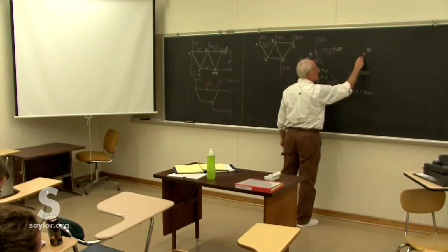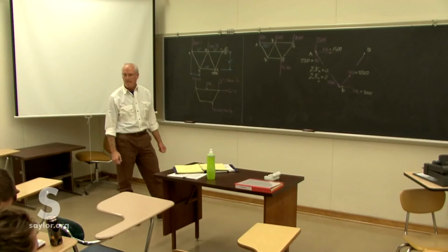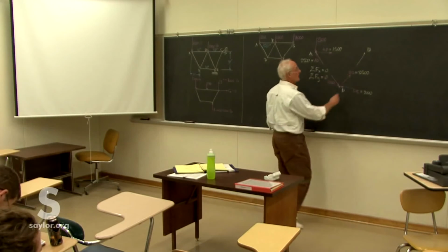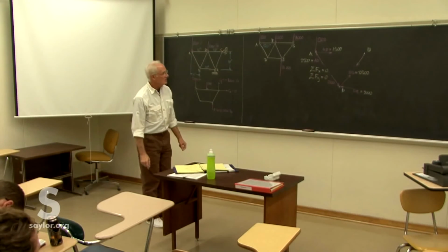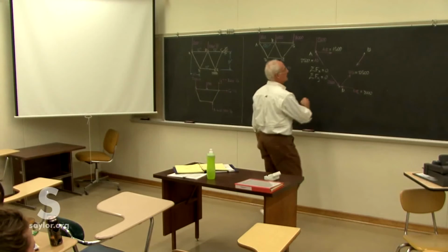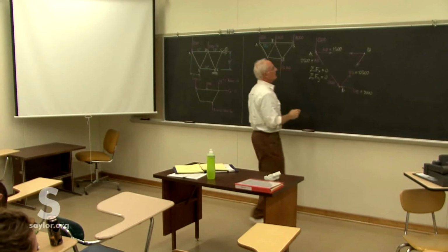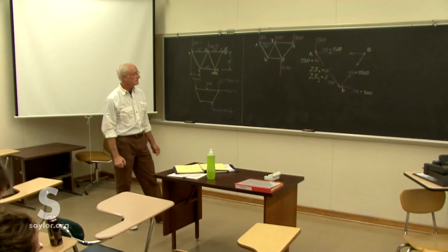Do we know anything about the force coming out of B? The one coming out of B pointing down to D. You know anything about it? Equal opposite direction. Yeah, it's got to do the opposite of what it's doing on the other end because it's a two-force member. In fact, we know the magnitude, the direction, and the angle of it, and the units. Same kind of thing here for that force that goes over the A. We already know it. We know everything about it.